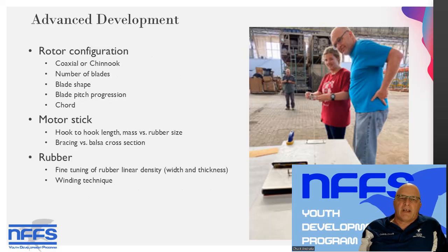The other advanced development would be your rotor configuration. Do you try a Chinook style? Number of blades, the blade shape, the blade pitch progression, whether it's a helical pitch like the X rotors, or a fixed pitch angle like the J&H, or something in between. That's something you can experiment with. The chord of the rotors.